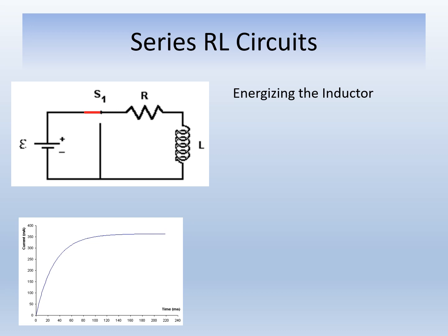Now there is flux. So there is a change to the flux, and we know from Faraday's law, the inductor will oppose the change and produce an induced voltage to cancel the change. So the inductor will induce a voltage to cancel the current that is passing through the inductor. So the current is completely stopped by the inductor just after turning the switch.